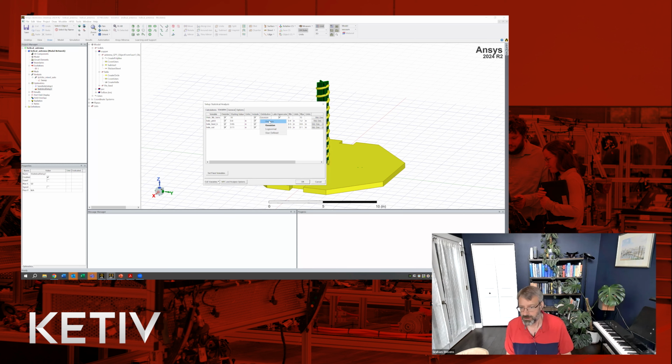The distribution of the input variables, the default is uniform, but you can change it to Gaussian or a normal distribution here, or log normal, or a user-defined distribution. And depending on what distributions you have, this is how you can pick or user define them. We can do an input relative to whether it's Latin hypercube sampling or not.